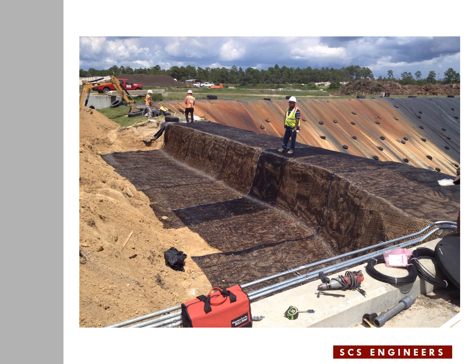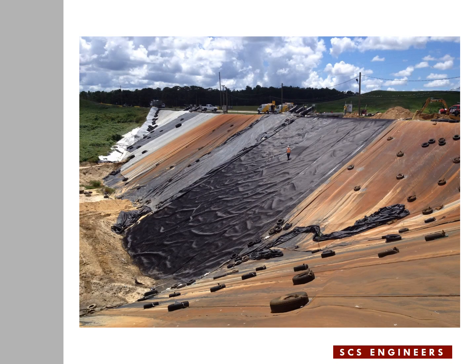Significant design considerations need to be made to the design of the anchor trenches for this type of application that has geogrid in them, because the slopes are steep and the interface friction angle between the geogrid and adjacent geosynthetics are fairly low. Here it shows the repair area completely covered with the second geogrid. Geogrid gets connected to the original geogrids on either side of the repair area and gets anchored in the larger anchor trench at the top of the slope.